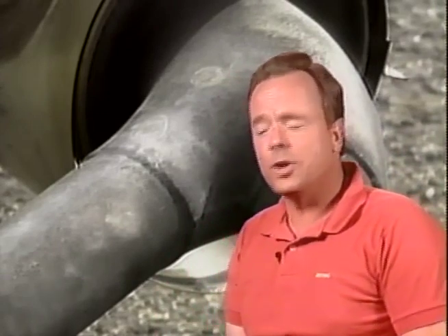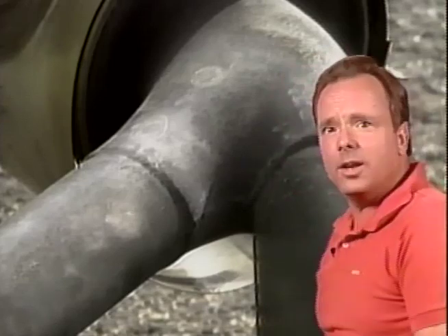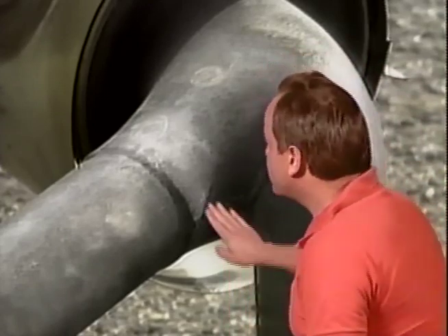All right, now, super mechanic, we need to know about the characteristics of a good gas weld on an exhaust stack. A good gas weld on an exhaust stack should be smooth and should taper off smoothly into the base metal. How do you look for a good weld? It tapers off smoothly into the base metal.